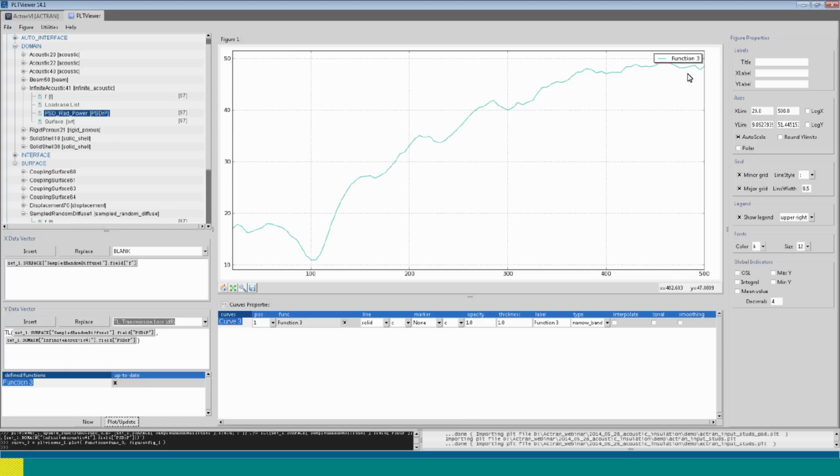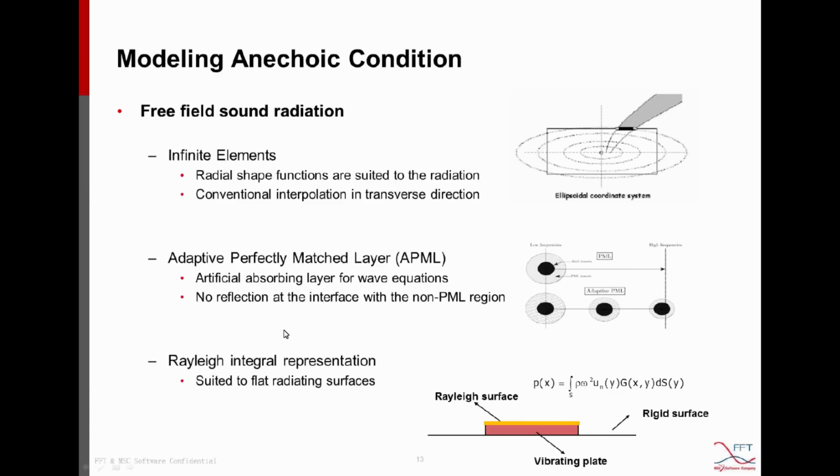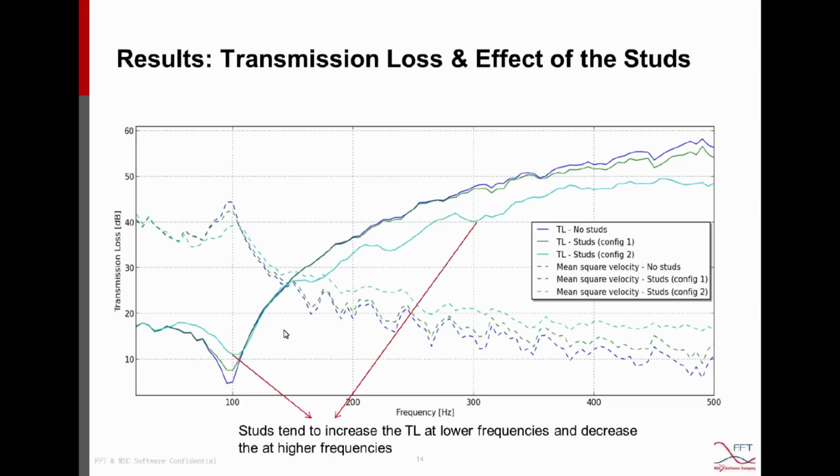And then, well, in this demo model, we didn't go to higher frequencies, which could be done by finite element modeling. Now, in higher frequencies, we will have some coincidence between the acoustic wavelengths and the structure wavelengths, and that will bring the curve down at the frequency that is called critical frequency, and then it will go up. But we will see that behavior in the case studies later on. Now, let's come back to the presentation.